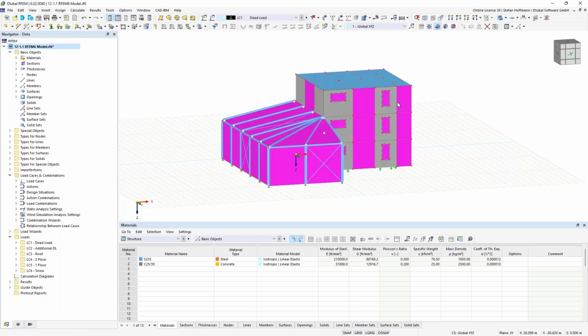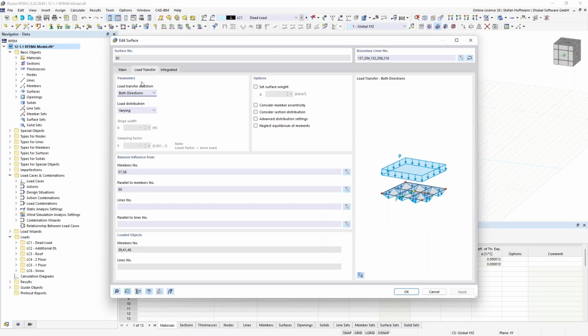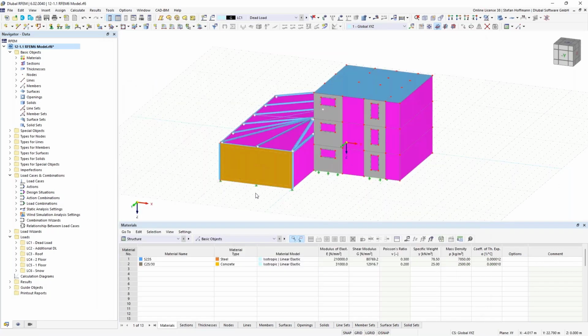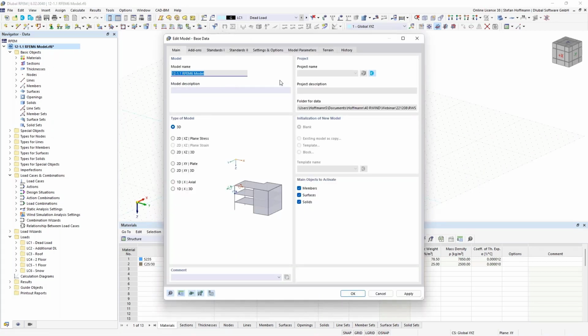And I have used our node transfer surfaces because I will have some facade, which is only giving the wind loads to the structure below and not giving any stiffness into my structure. So for my purpose, I will use those purple surfaces. And I have, of course, then defined whether some members are not carrying loads, like those tension members in here, or whether my couplings should get some force or not. So this is the stuff I have introduced, and mainly, I will now show you what inputs can be done to RWIND and RFEM 6 directly.